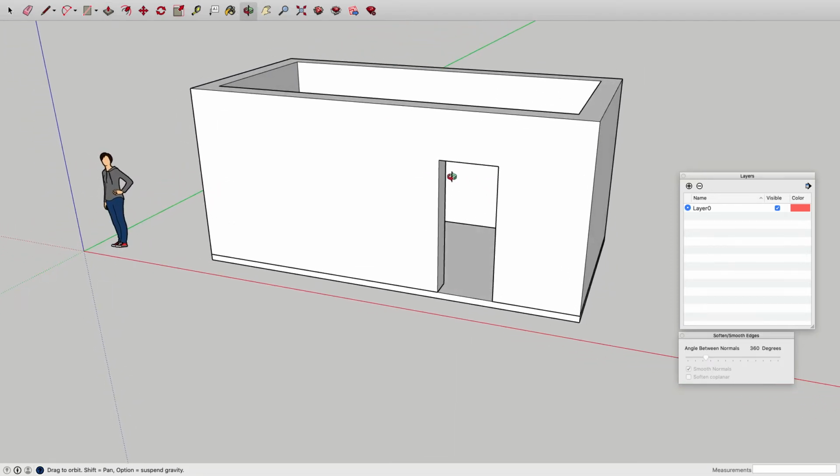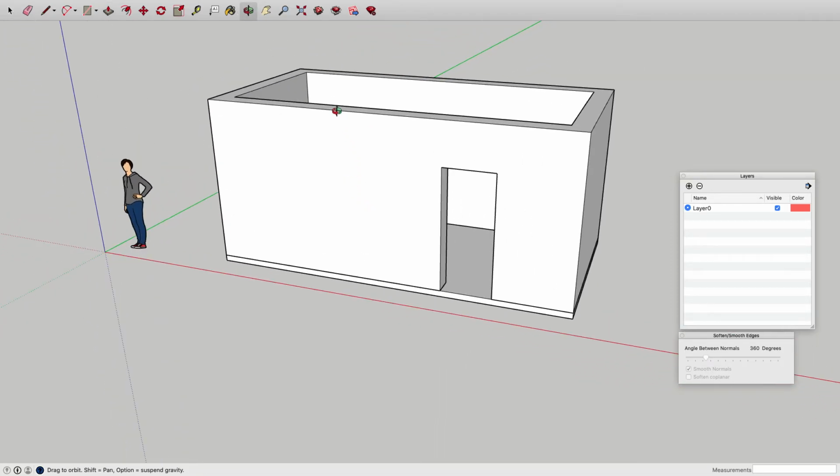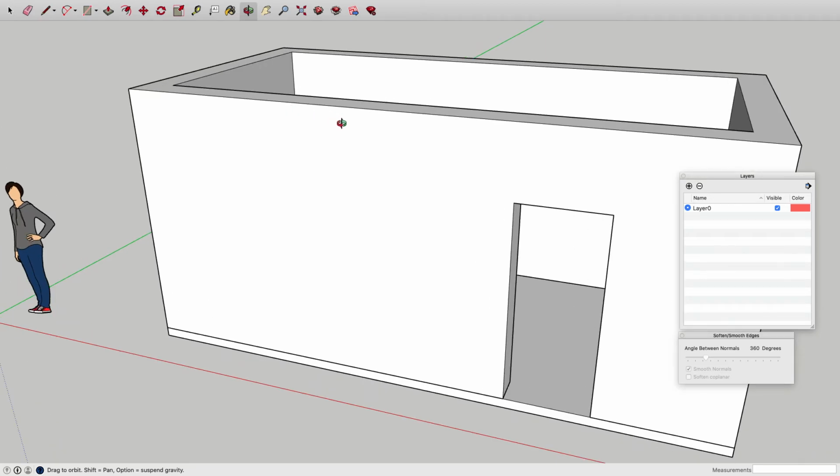All right, another one is I want to do a window, put a window in. Right, so let's move more in here so I can see a little bit better. Right, nice and big. So I want the window to be a nice, decent size, and proper to what it would be according to this code, okay? I'm going to use the tape measure tool to make a guide. I'm going to click on this corner here, and you see how it's red? How it snaps to as a red, that means that it's a horizontal line on that surface.